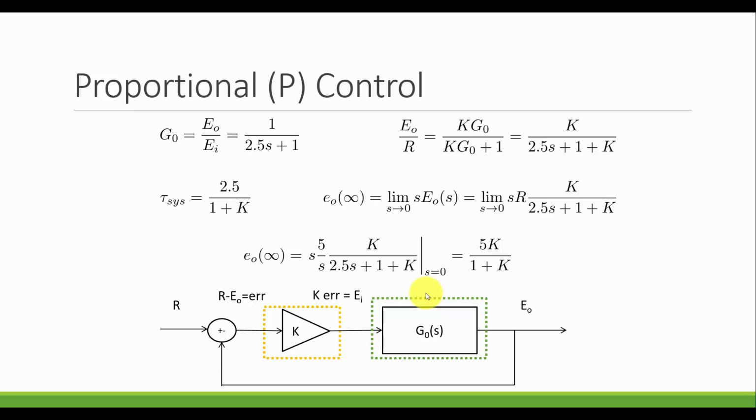really what it's going to do is modify our closed loop transfer function, and we can still accommodate that, but it's going to be more difficult than we want to get to in this introduction to control. So just be aware the sensor and the actuator in general will contribute to the closed loop transfer function. We will ignore them though for now.